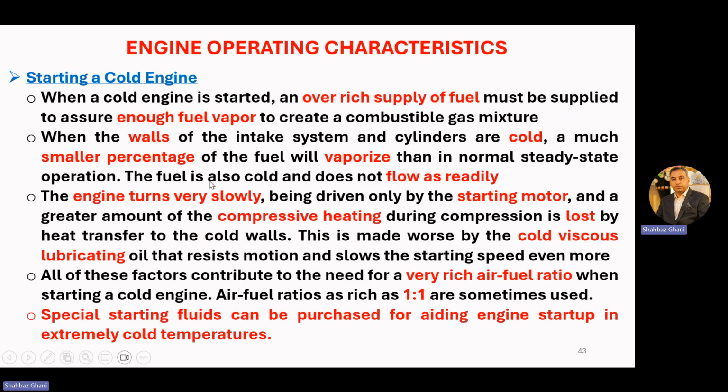Now, the last condition, starting a cold engine. When a cold engine is started, an over-rich supply of fuel must be supplied to assure enough fuel vapor to create a combustible gas mixture. So when we have a cold start, or the engine is very cold in winter conditions, an over-rich supply of fuel must be supplied to assure enough fuel vapors to create a combustible gas mixture.